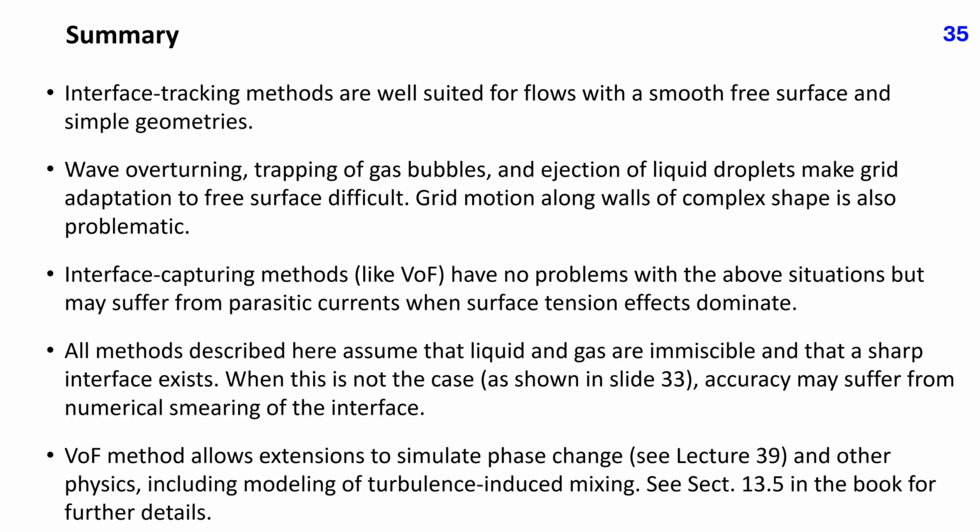When this is not the case, as shown in slide 33, accuracy may suffer from numerical smearing of the interface. VOF methods allow extensions to simulate phase change, see lecture 39, and other physics, including modeling of turbulence-induced mixing. See section 13.5 in the book for further details.